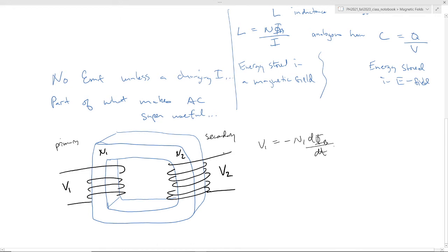You have to have a change in current in order to cause that in the solenoid example. But just backing up and talking about the flux generally, if you make this out of a highly permeable magnetic material, you're basically going to get the same or very similar flux in both coils. And so what that means is that the voltage in 2 would look like this. But the fluxes are the same. So we could solve this for flux.